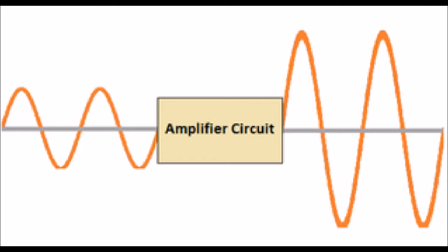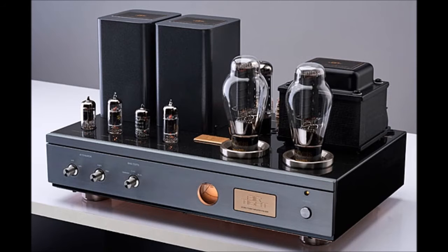The aim of any small signal amplifier is to amplify all of its input signal with the minimum amount of distortion possible to the output signal, or in other words, the output signal must be an exact reproduction of the input signal, but only bigger, or in amplified form. To obtain low distortion when used as an amplifier, the operating Q point needs to be correctly selected. This is in fact the DC operating point of the amplifier, and its position may be established at any point along the load line by a suitable biasing arrangement.